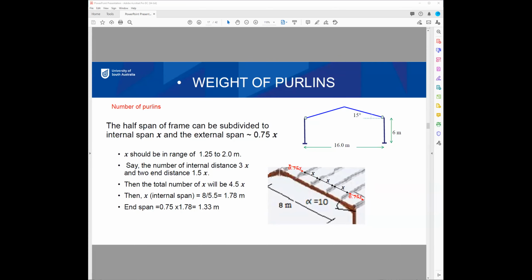Yeah, I think the dead load calculation goes first, isn't it? You assume a section of the beam, the rafter, and then calculate everything from top to the rafter. Yes, this is the concept of design. You need to have a fair initial assumption for the section first to use it in your design, and then calculate all the load depending on this section.